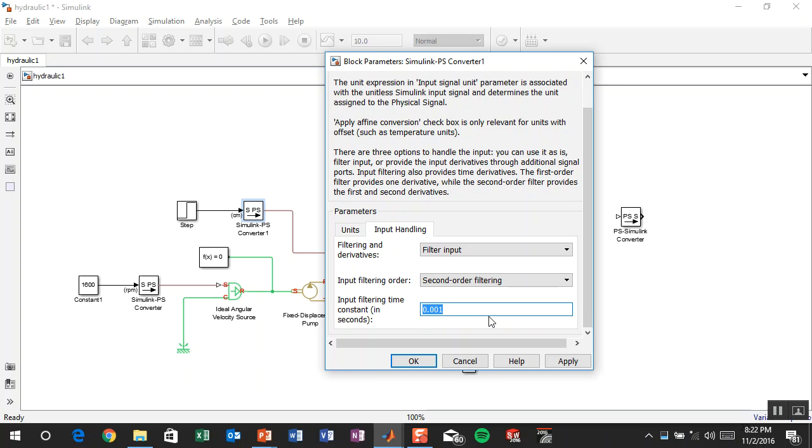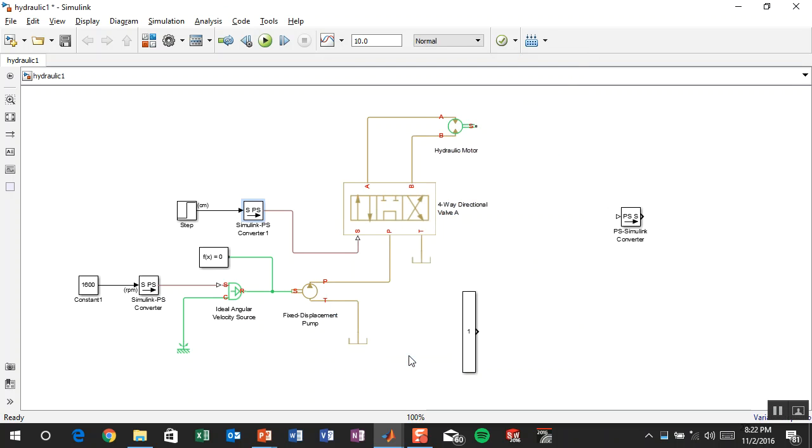And oh, whoops, I forgot that I had second order filtering. Because once you build the model, after a while, you don't look at every parameter of every component. So I feel like it makes more sense when you're doing something longer term to invest that little bit of time and use an explicit block. But because we're low on time here, I'm going to say this can move as fast as 1/20th of a second. And that's all I want to do. So that's in centimeters, that's good. Okay, so all this stuff is all good now.